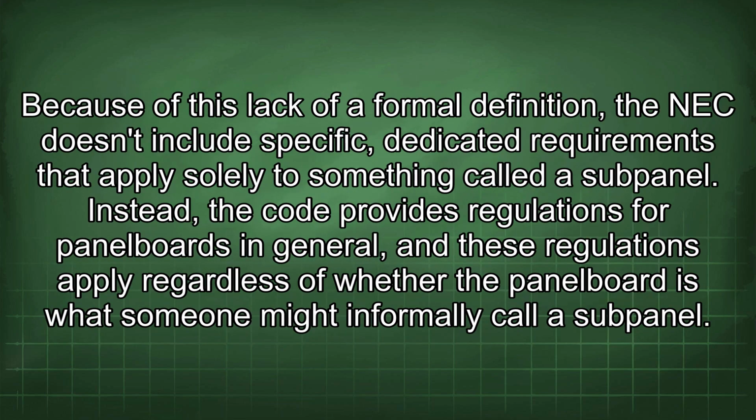Because of this lack of a formal definition, the NEC doesn't include specific, dedicated requirements that apply solely to something called a subpanel. Instead, the code provides regulations for panel boards in general, and these regulations apply regardless of whether the panel board is what someone might informally call a subpanel.